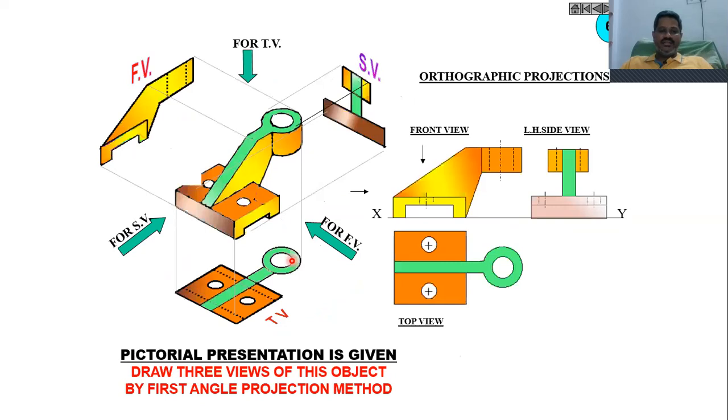Then we have seen the other component. Let me go back. This component also we have seen, but please make a correction: in this case it needs to represent two dotted lines here, because we have a projection, a depression here that is not shown here. Please make a correction here. And similarly, dotted lines also need to be represented here, that is also not shown here. So two dotted lines, the hollowness needs to be represented in this case, that is not shown here.